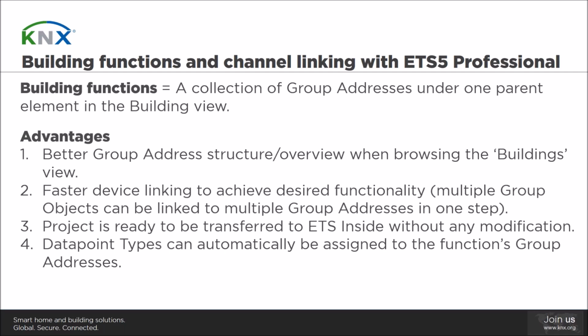The benefits of having functions in a project are quite similar to those of having channels, and in fact, the combination of channels and functions in a project is what maximizes the benefits for the ETS users. As said before, linking device channels to functions can actually perform multiple group object to group address linking with one only step, which as such can impressively reduce the time to design a project.